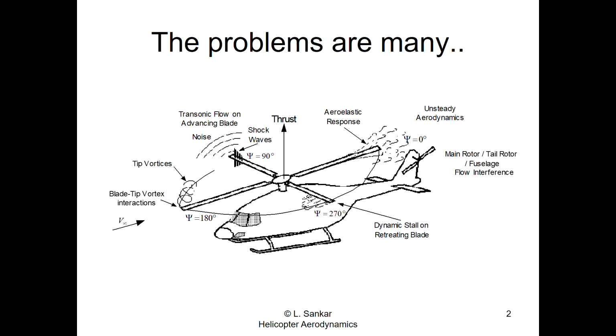So in high-speed forward flight, we get shock waves on the tips, which are bad for a number of reasons. It produces wave drag. It produces a nose-down twist of the blade. It produces noise that propagates forward and away from the rotor. You have hinges, and perhaps a cyclical pitch control to balance the load.